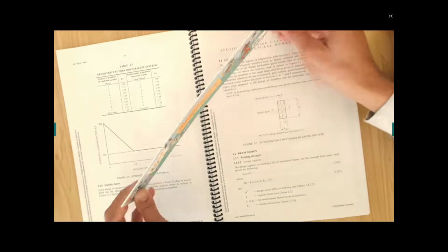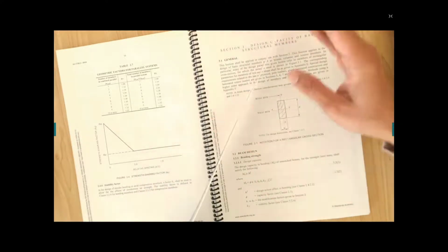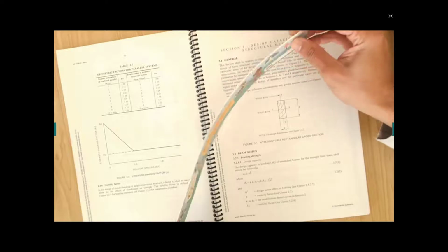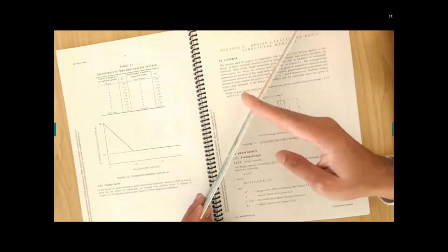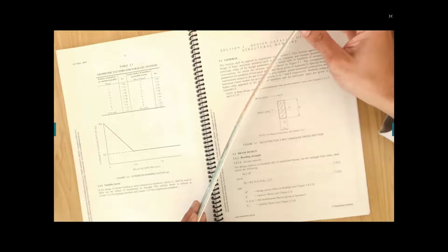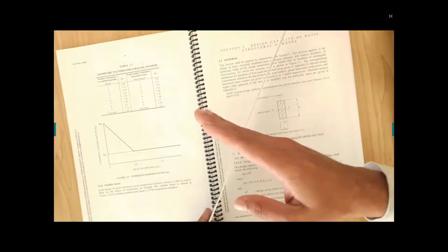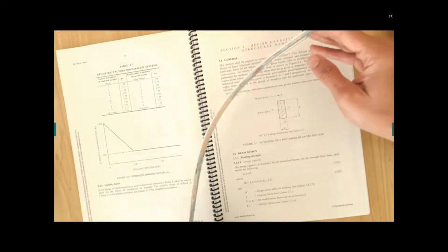So if you have a beam and you don't put in the lateral restraint, then it does this. It will just laterally torsionally buckle. The timber beam will do the same. If I put the lateral restraint in here, then this beam is not going to have this lateral torsional buckling. It's like kicking it out from its original position. It's very flexible, so you can see.